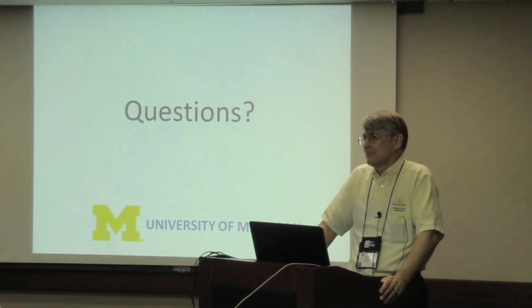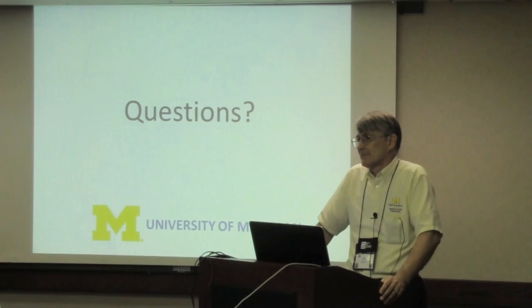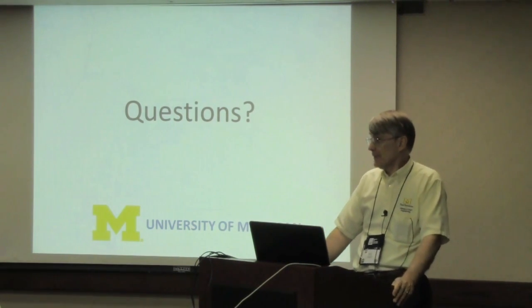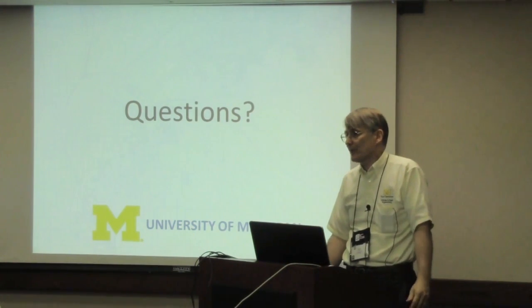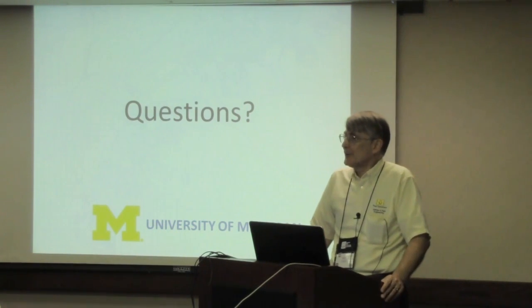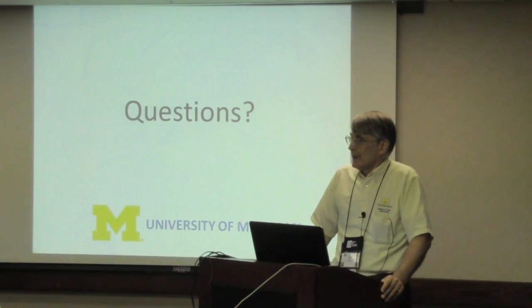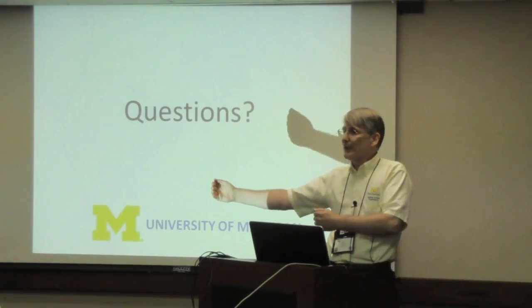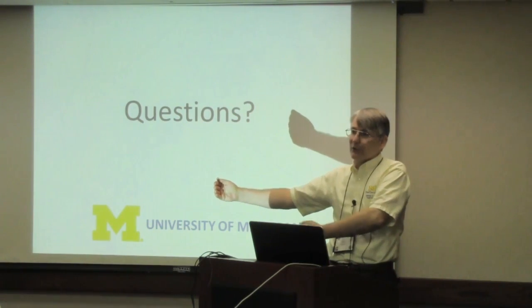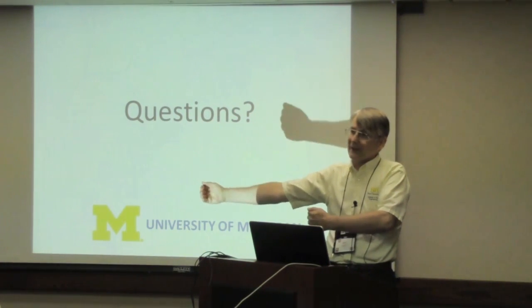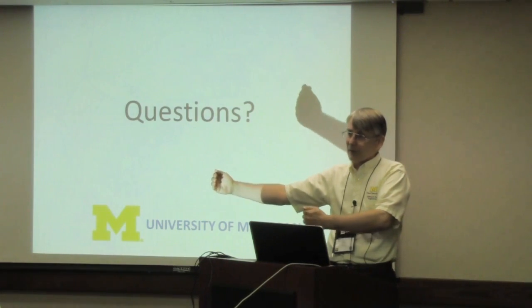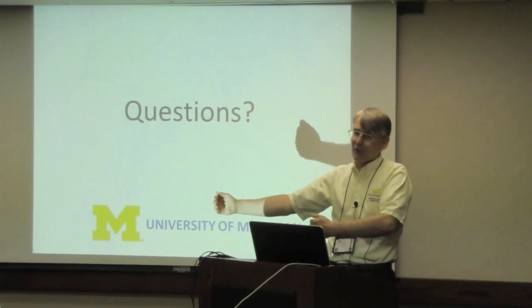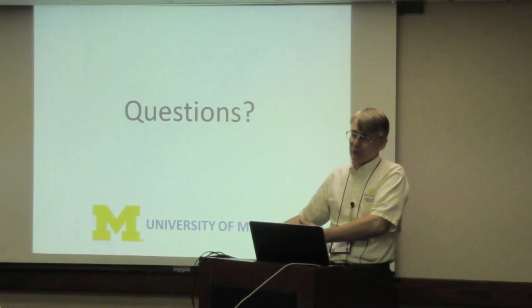Yes, sir. Do you treat your tunnel more like a building than a utility infrastructure? We treat it like a building. Our tunnels, we've got 6 miles of tunnels. It's broken down into 9 separate buildings. And then we've done fake rooms in there. We've got stanchions that hold the pipes up. Stanchions are typically between 10 and 12 feet. A stanchion will start the beginning of a room and the room will end at the beginning of the next stanchion. So we've created rooms for each one of those. All the assets are located in those rooms.